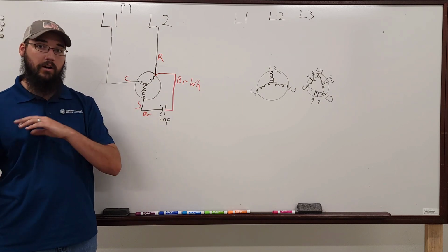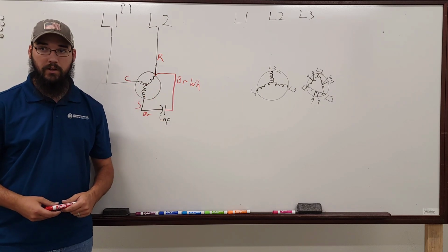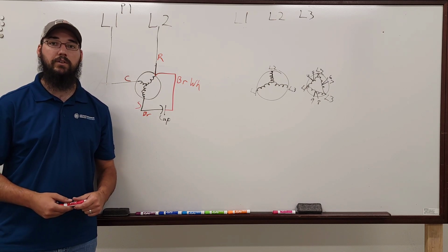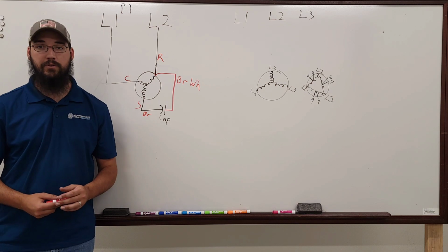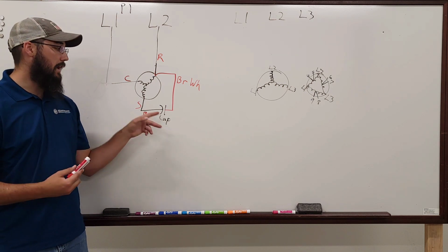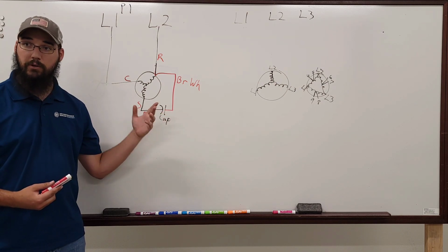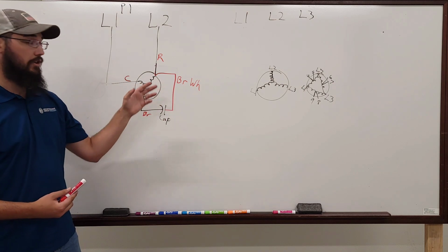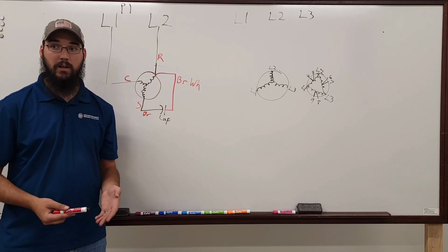You can take a 3-wire out and put a 4-wire in. Most of the universal motors that you buy at the supply house, that many companies keep on their truck stock, are 4-wire motors. So it doesn't matter. What matters is you'll need a jumper versus not, right? So in a 3-wire configuration, and you'll see this in condenser fan motors too, this is the same exact principle.